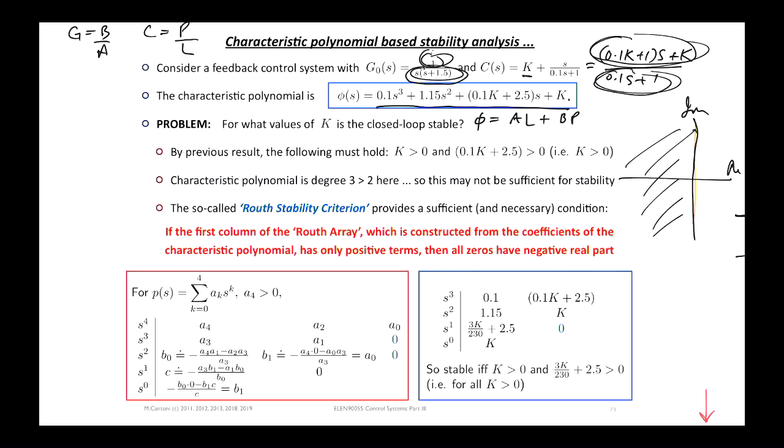Right, whereas here, it doesn't matter what value K is, it goes to infinity no matter what K is. So even when K was small, we've got 0 error, right? And the reason is because this here is giving you infinite gain at DC, whereas here, increasing K pushes this line up. So it increases the gain at DC, but it's never infinite, right? Whereas having the s will make it